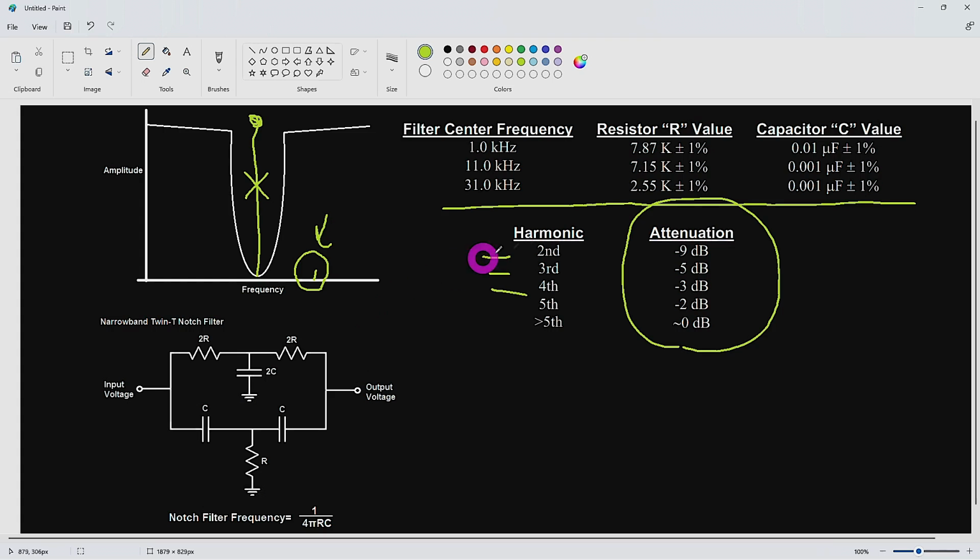Now, one other thing to keep in mind is that even though these are just resistors and capacitors, it does not mean they're linear. So you have to choose these carefully. In the manual, they recommend thin film resistors and ceramic capacitors, which should have hopefully the highest linearity. Now, at 1 volt peak to peak or 1 volt RMS, which is the value we're interested in measuring, that's the highest THD this instrument can give you, so this shouldn't be too much of a problem.